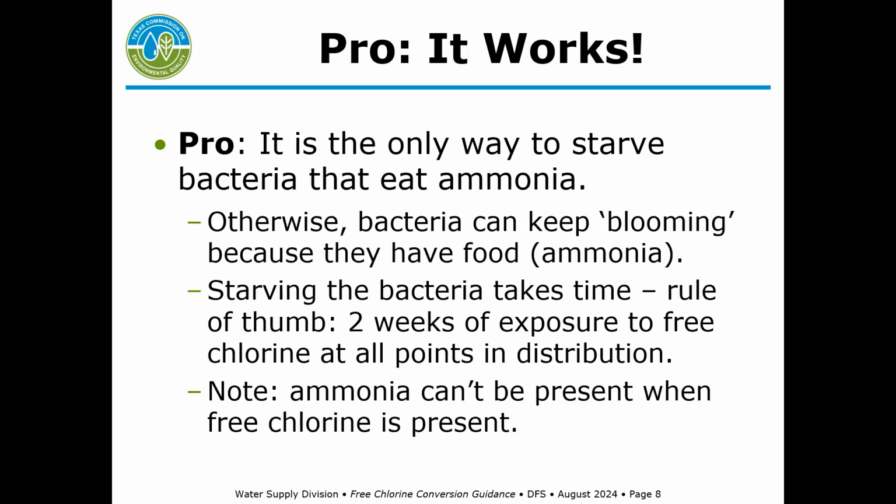Let's talk about some pros and some cons, but a pro is it works. It's the only way to starve the bacteria that eat ammonia. Otherwise they can keep going and blooming and making the nitrification worse. As a rule of thumb, starving bacteria takes some time. I would recommend that at all points in your distribution system during a conversion, you try to get at least 2 weeks of exposure to free chlorine. Don't do it in 1 week and only get a couple of days of free chlorine exposure at some points, because it takes longer than that to starve the bacteria.